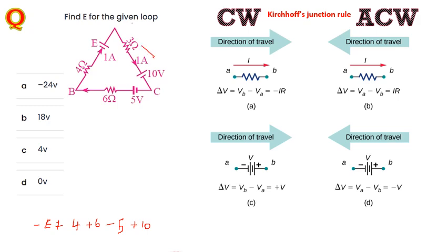Now this one again, here this is 3 ohm resistance. Current direction here is this direction. Current direction, opposite direction you are going to measure. So this is plus. I just mentioned here, resistance here is 3 and current here is 1. So 3 into 1 is 3. That one will be equal to 0.